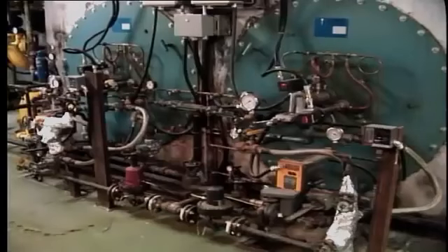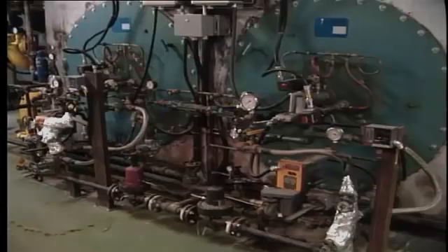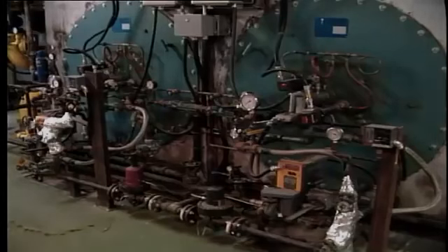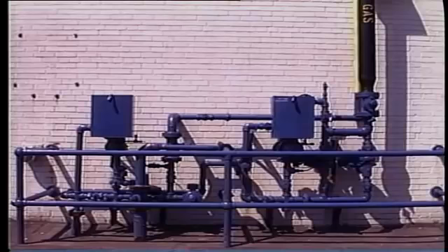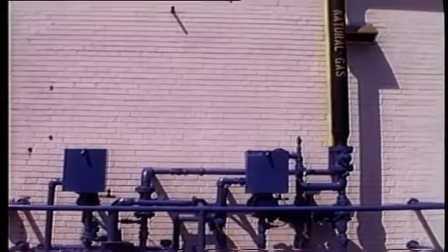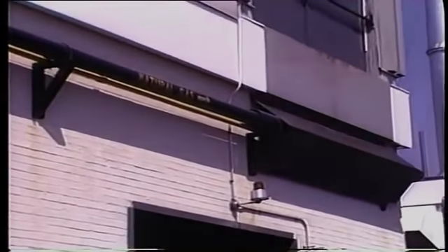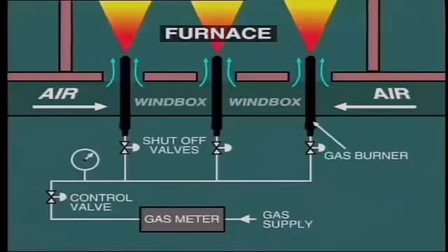popular fuel, natural gas. Firing with natural gas has some similarities to oil firing, and it is certainly the simplest fuel of all to burn. In most installations, the gas requires no preparation at all, as it is delivered under pressure directly from the supplier. Therefore, no storage facilities are required. The supply is metered at the incoming station, where its pressure is reduced to that suitable for the boiler. The gas is then supplied through a control valve to all of the burners.